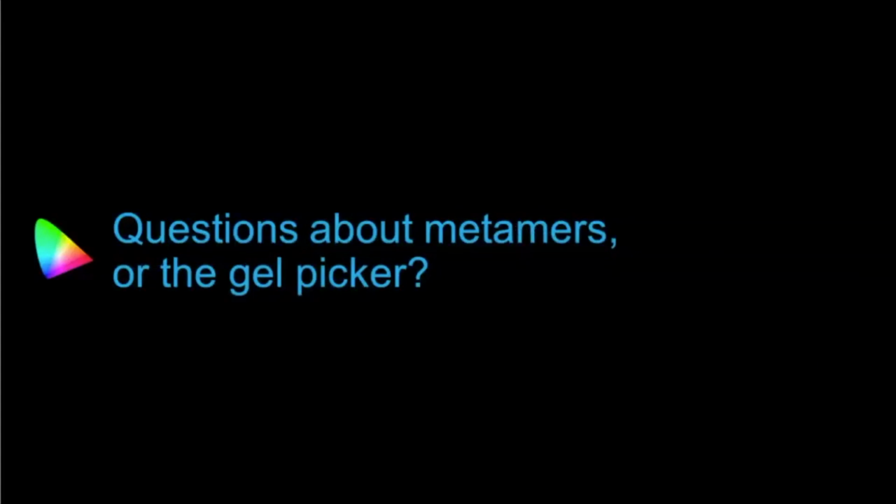And I think this is actually the very last thing you touched on, but I think it's worth noting. How does the brightest spectral hybrid switcher work? Do you change it and then reselect the gel to update the chosen metamer? Yeah, that's exactly it. So if you don't like the brightest, when you click on R72, click it over to Spectral and click on R72 again, and it will apply that to the fixture. Click it over to hybrid and redo it. If you're using that a lot, or you know there's gels that you're going to be using often, maybe color palletize those things ahead of time so that you have a couple of color palettes you can just pop between. It's an option. We're just storing the parameter values at that point, so it doesn't matter.